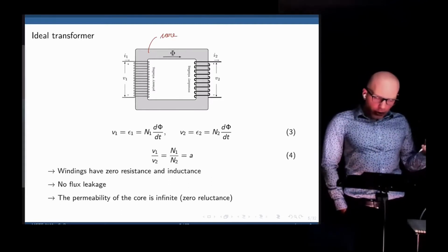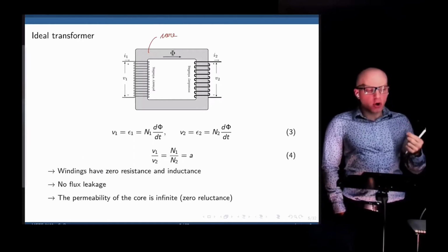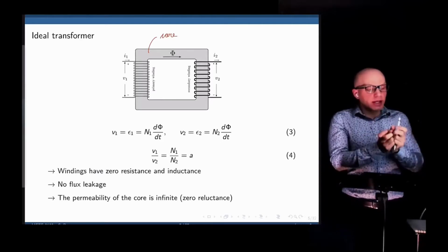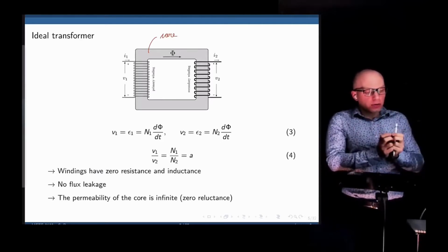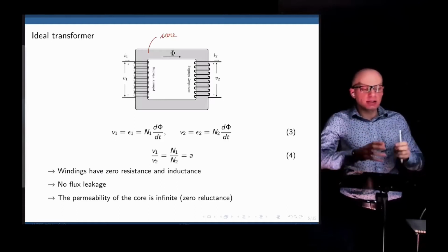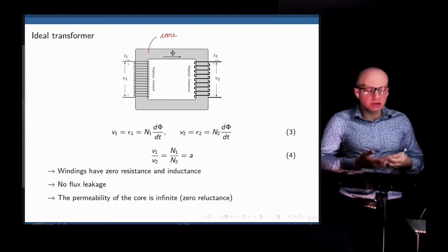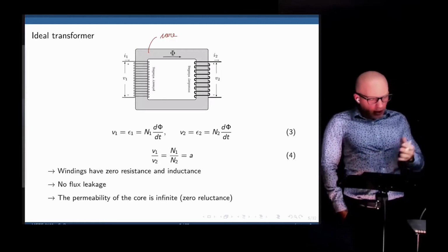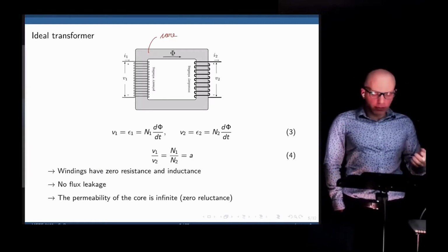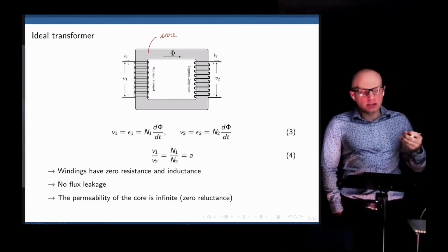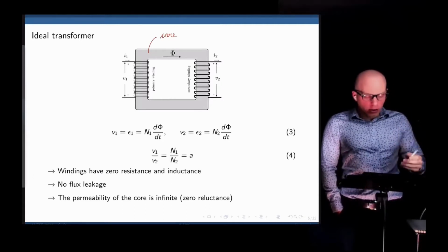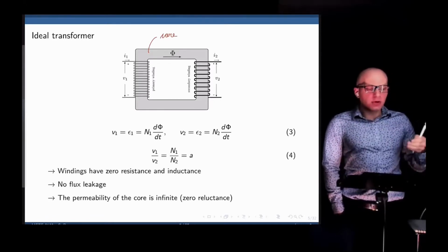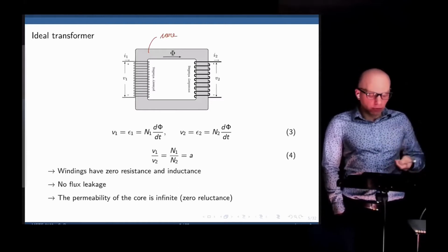So now we have two coils. We have a shared magnetic core of a high permeability. The reason, again, is that way we can concentrate the magnetic field in the core. The EMF required to establish a flux is a lot lower than the EMF required to establish a flux in the open air, right, compared to the very first configuration. Now we have these two windings here. Each of them, the primary and the secondary winding, create its own magnetic flux. Or let's put it this way, if there is a magnetic flux in the core, then each wire is subjected to its own electromotive force.